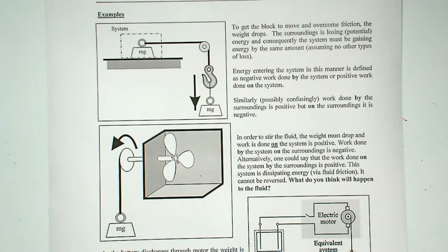And you may not really care about it at this stage, or you might think, well, that's not really important, but when we do some examples, you see actually that it makes a huge difference, because at the end of the calculation, when you find, for example, that the work is equal to 40 joules, if the work actually was negative, then it should be minus 40 joules. And when the problem becomes more complicated, if you don't take the sign into account, then you will miscalculate the overall work and heat in the system.